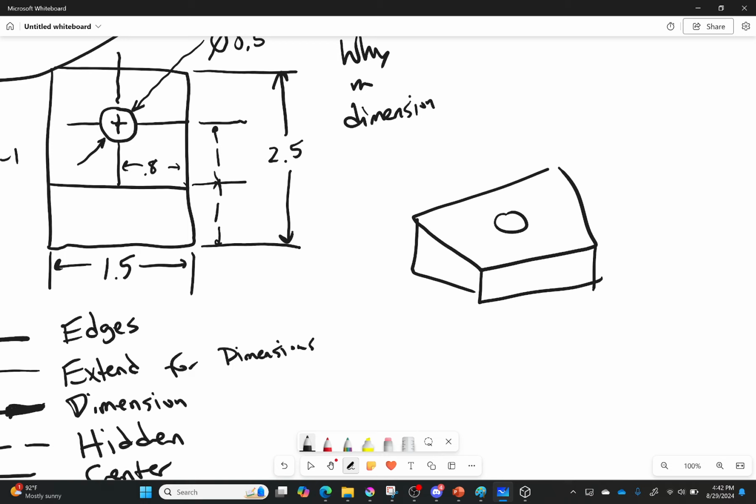I want you to take a tape measure, you know, that kind of thing like this, and I want you to measure all its dimensions, and I want you to draw something like this. And add all of your dimensions into it, all of the lines, the center lines, hidden lines, everything. And give me a good drawing of that object. If you do that, you'll be another step closer to understanding what we're going to be going through when we get to SolidWorks.